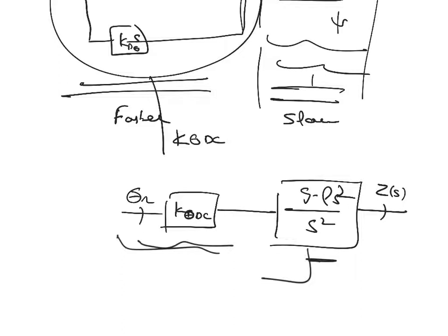We are designing it, right? If you remember, we chose an omega n for designing the PID loop for the first loop. So it was, let's say, 4.4. Now when I design the second loop, I'm choosing that omega n to be 10 times less than that frequency, let's say. So purposefully that separation has been maintained.